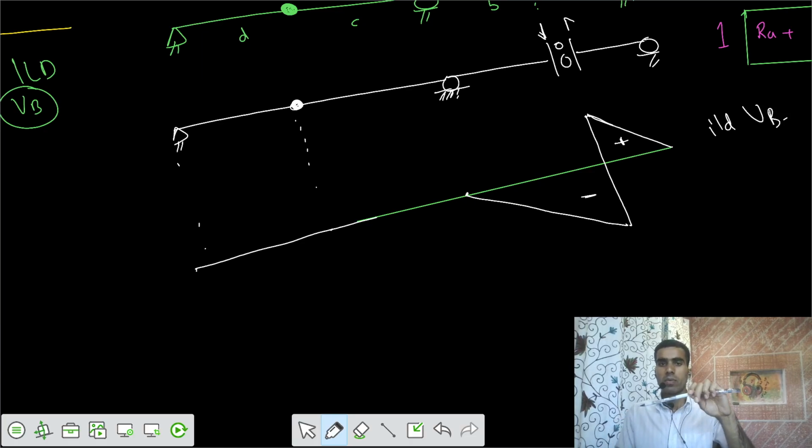To get the understanding, let's say this is X, Y, Z, and this is alpha. Once alpha has gone down, and at the support, let's say this is some support Z, alpha has gone down, but this support Z has to remain at the location of Z itself. It won't go anywhere. So Z is here. But if you talk about point Y, it is here at the internal hinge. So remove that other part of XY. Point Y has reached up with respect to the main line.